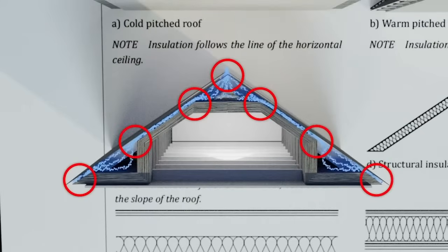Where a roof transitions from cold to warm and vice versa, it's important to ensure the air can move between the various areas uninhibited, which can make detailing both ventilation and the position of AVCL membranes challenging. This is especially the case where dormers, complex roof shapes, and subdividing walls are present.